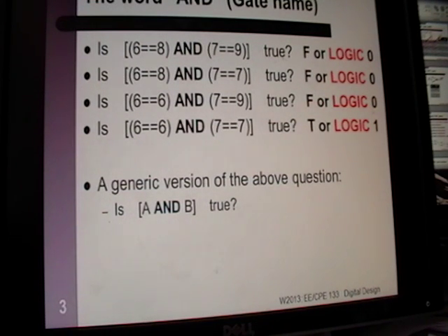In a circuit, for example, there's a port on some of the older computers and various other devices. I think they're still available in the lab. But a plus 3 to 15 volts, I believe, means false for the RS-232 port, and a negative 3 to negative 15 means true. So it's whatever the designer decides to have represent true or represent false. So this 0 and 1 right here has nothing to do with the electrical properties of your circuit.